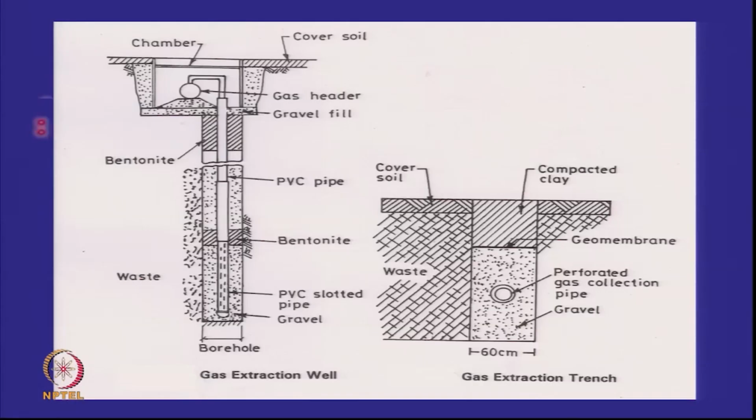So this is a gas extraction well which will be used in an active or a passive case, like a tube well. Like a tube well, perforated pipe, gravel pack around it, a pipe which takes you to the top and connects to a gas header pipe. The header pipe goes to a suction pump or a blower which pulls in the gas if it is active, or the header pipe goes to a vent if it is passive.